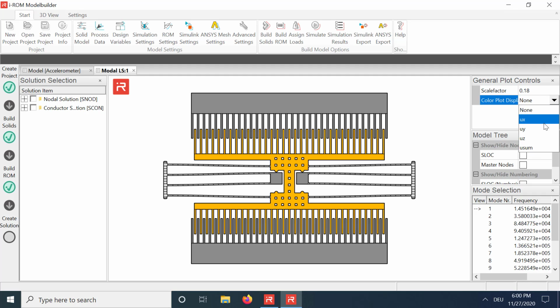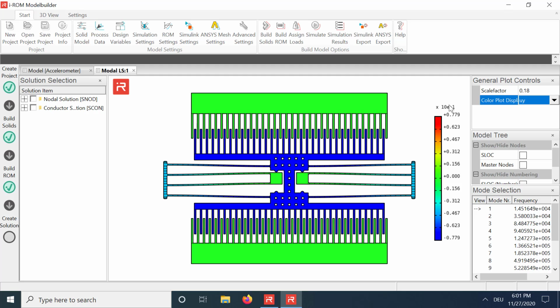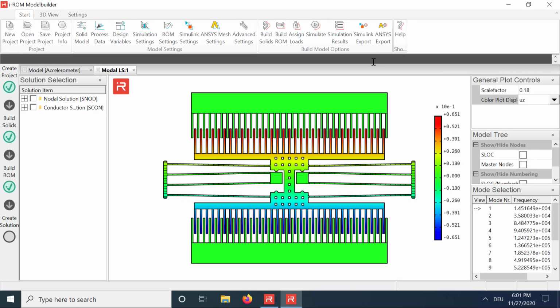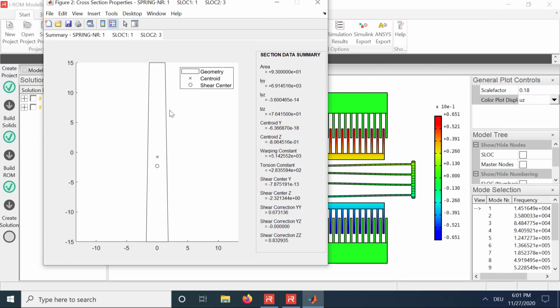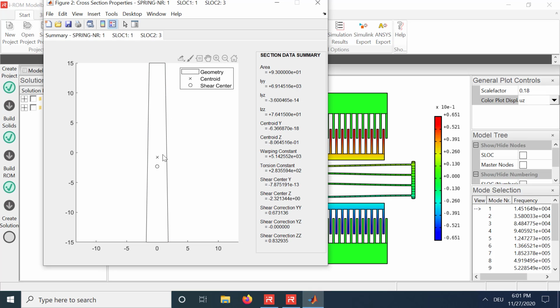The amplitudes in the y direction are scaled to 7.8 micrometer. It produces approximately 65 nanometer amplitudes in the out-of-plane direction. The mass body rotates slightly around the x-axis. Torsional vibrations are caused by the trapezoidal cross-sections of the Timoshenko beam elements. The center of gravity is higher than the shear center, which results in a torque with each oscillation cycle.